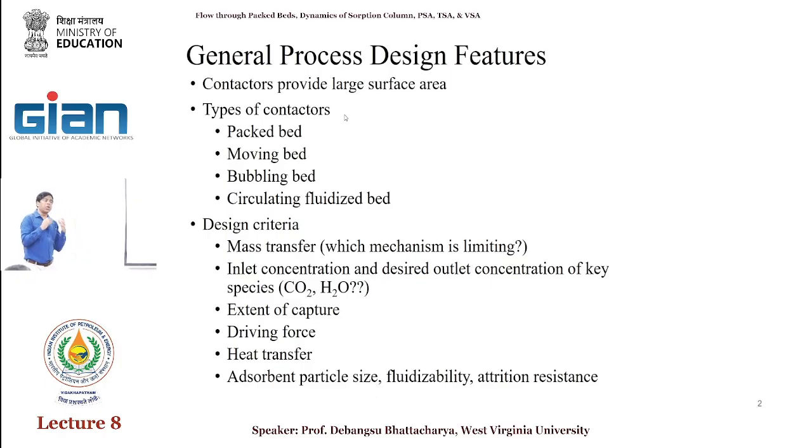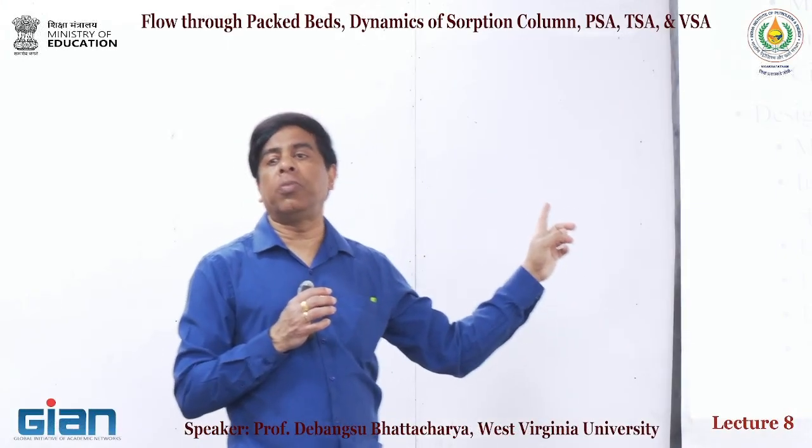When you go from the powder to a particle, you might actually land up with a lot of mass transfer resistances and heat transfer resistances. So it's not arbitrary. That is where the expertise of the people who develop commercial catalysts lies: how to take the lab scale powder and move it to real life operations without creating mass transfer resistances. So that's a design criteria that you have to keep in mind.